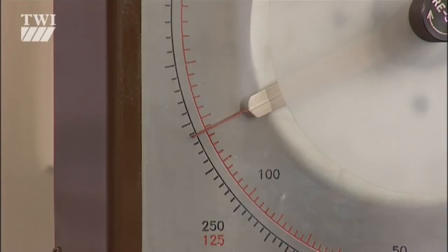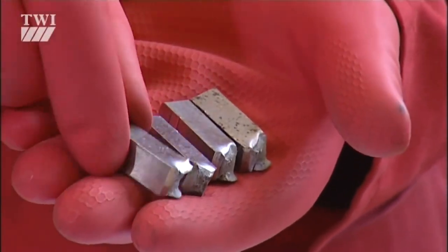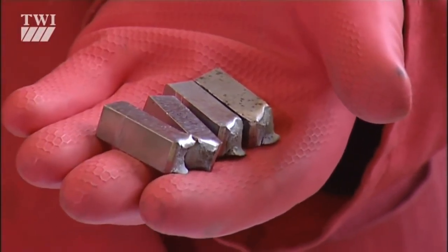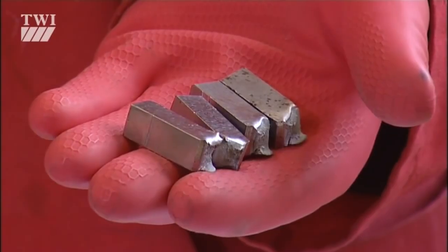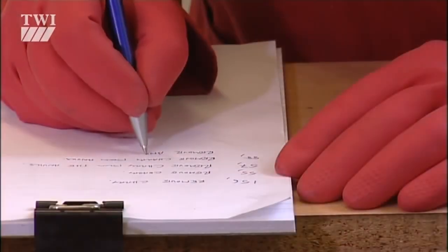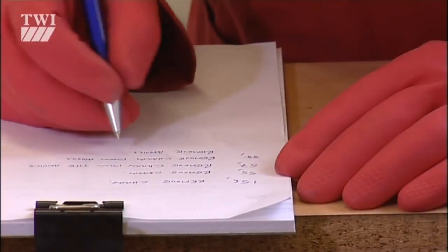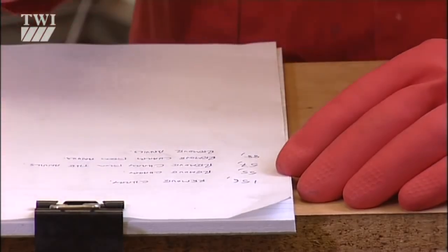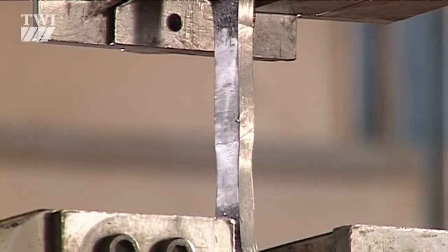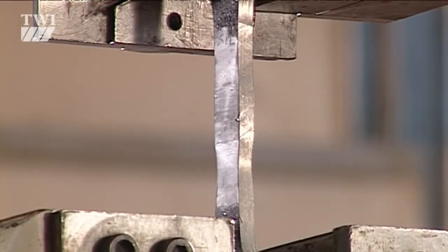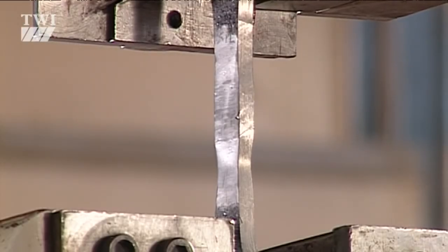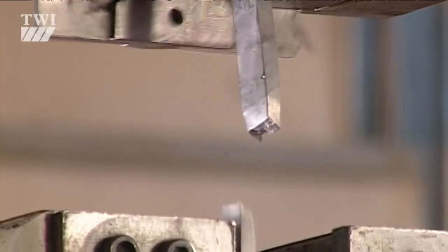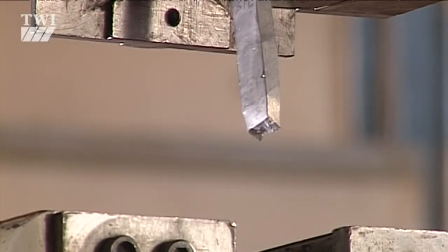the material. The amount of energy absorbed in fracturing the piece gives an indication of the notch toughness of the test material. If a small amount of energy is absorbed, the material is brittle. Ductile materials absorb a great deal of energy. Experience indicates that a specified energy absorbed is required to avoid brittle fracture.